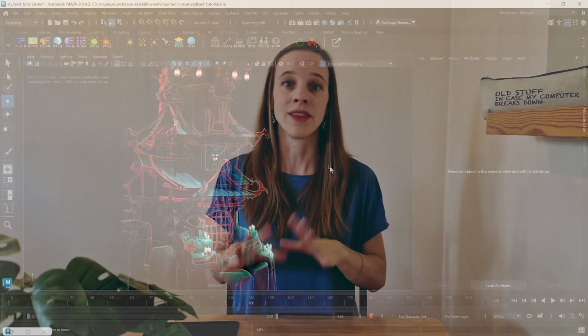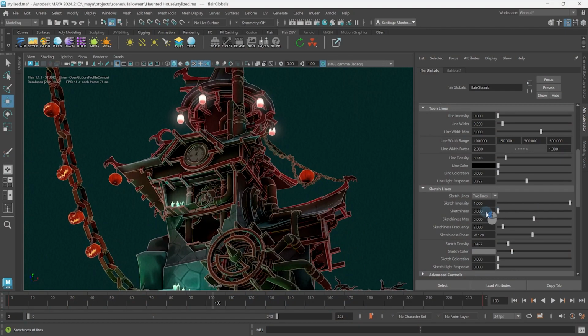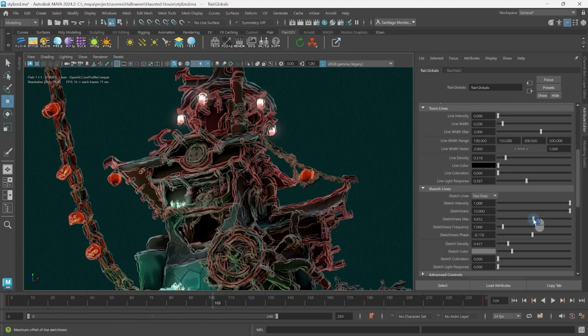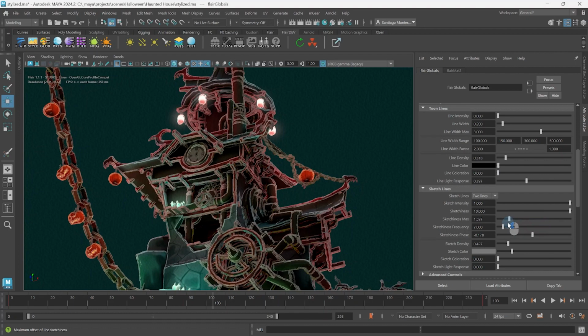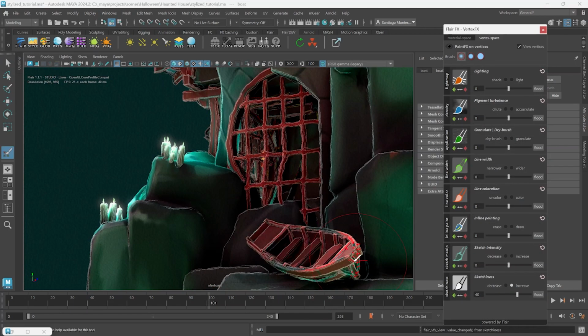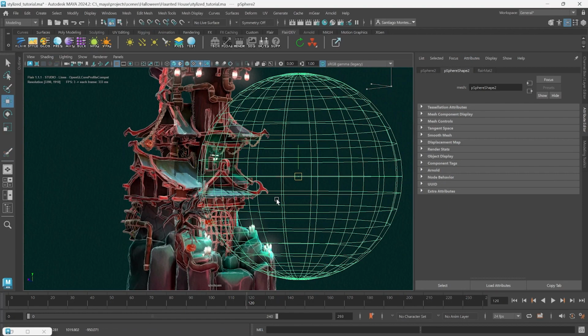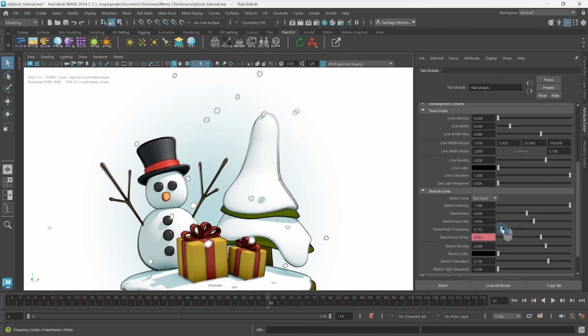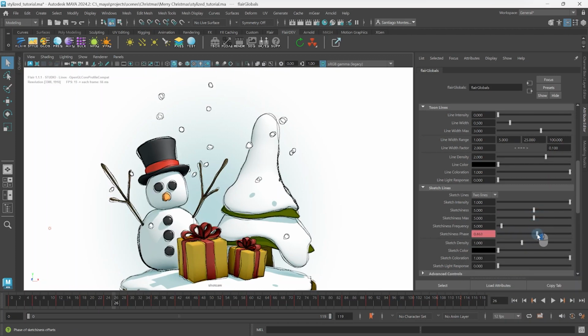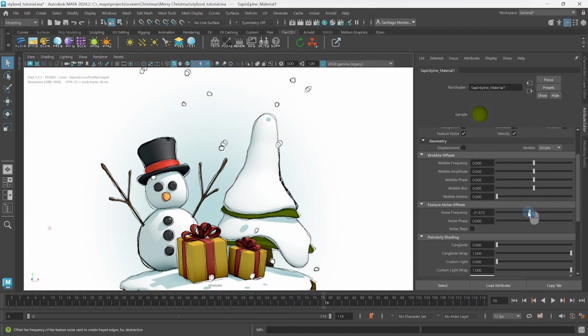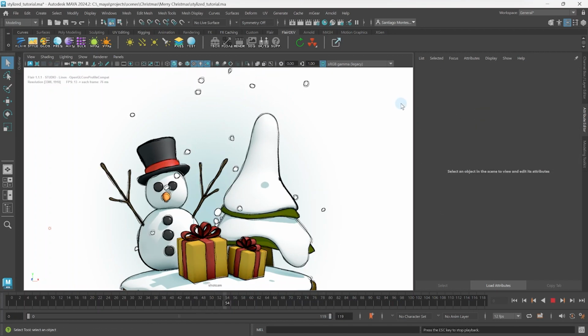This covers the basics of sketchiness control. We learned how to set the global sketchiness and tune the global Sketchiness Max to control the amount of offset of sketch lines. We also learned how to further art direct the sketchiness of lines with the art direction tools within Flair. In the next tutorial, we will learn how to set the sketchiness frequency and phase globally and per material so that sketch lines behave differently throughout the scene, even over time.